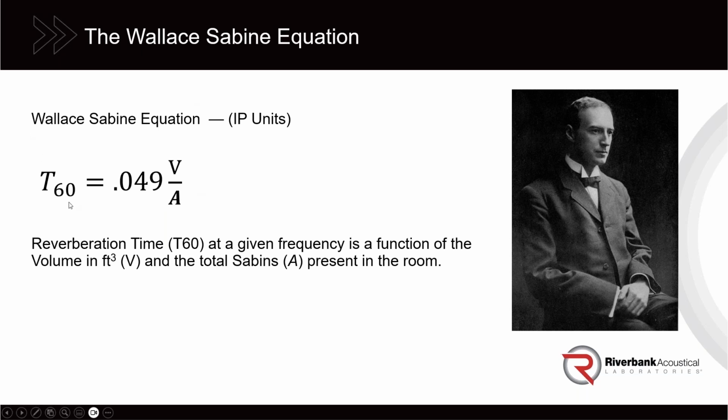So you could measure an existing room, know its reverb time, and if you had a target reverb time, you could solve for the increase in Sabins needed to get from the current reverb time to the target for a specific room. This was the start of acoustical consulting. This was the start of acoustical materials, and that's where it all began.